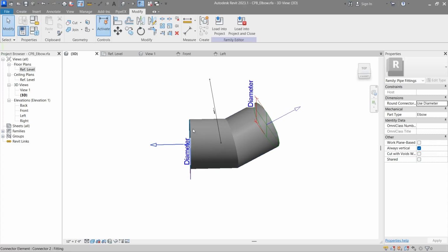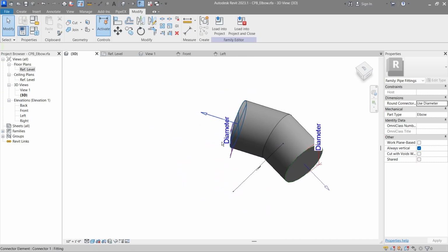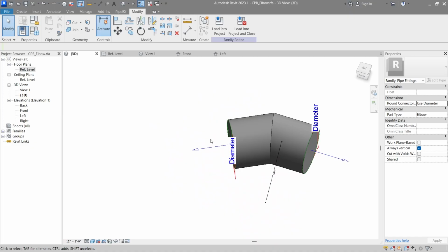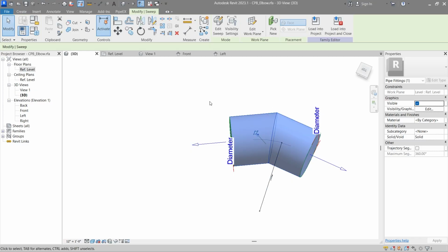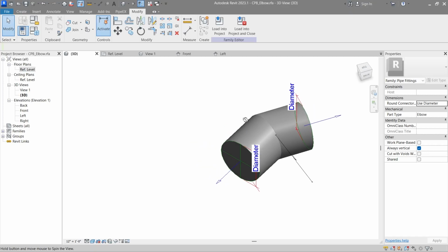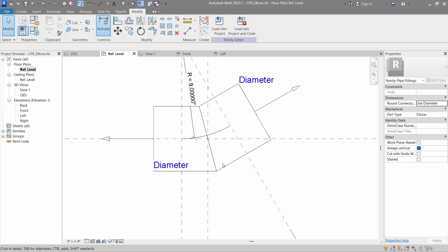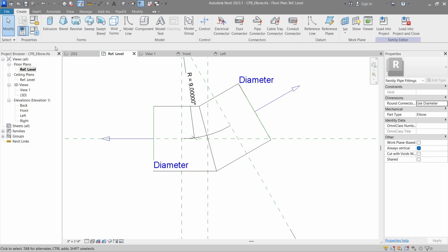And basically that's it. So probably you will have a question, why do we need to attach it to this shape? The answer is simple, because when we are going to adjust L1 or L2, this shape will move, but not the shape of the main elbow. So that's why it should be attached to this base. So next step will be to create an elbow over here that will be shown as actual elbow, yeah? Or the bend turn. You can call whatever you want.